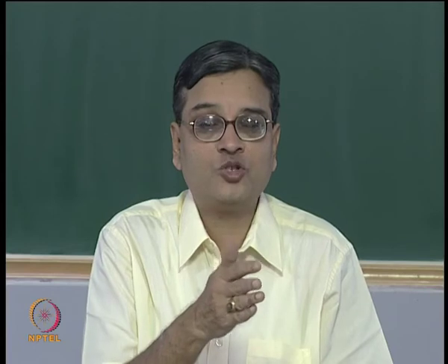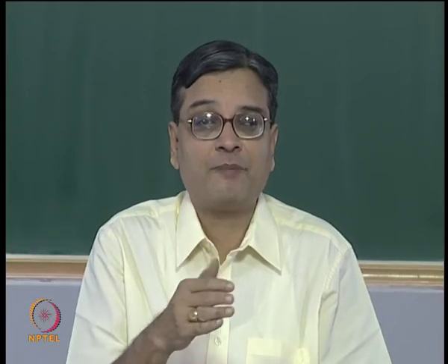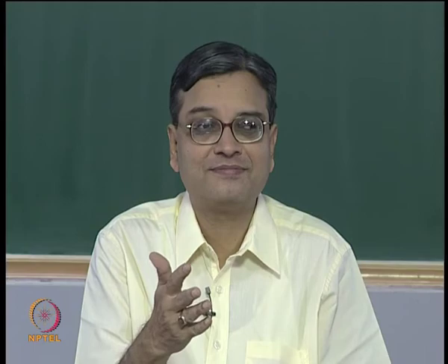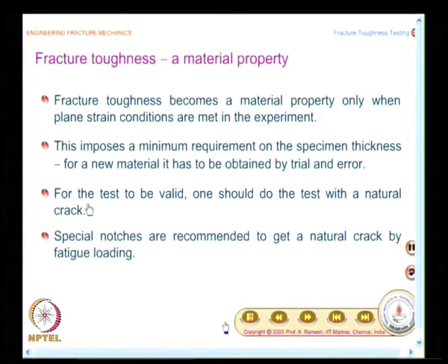Keep in mind, a tension test is very simple. Even the specimen preparation is far simpler in the case of a tension test. Once you come to fracture toughness testing, even specimen preparation is quite involved. And imagine, at the end of the test, if plane strain condition is not satisfied, you have to scrap the test. That is too expensive. We will see how people have handled these scenarios.